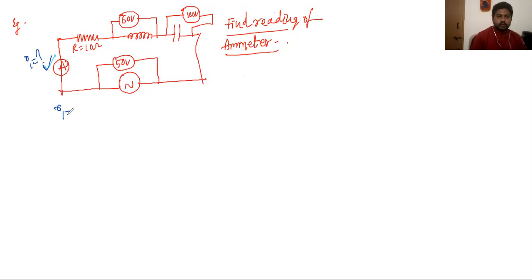So I is equal to E by Z. What is Z? That's impedance. And before that, you know this E. This 50 volt is the RMS voltage of the circuit, E. Here itself, let us find that E. E is equal to square root of VR square plus VC minus VL whole square.